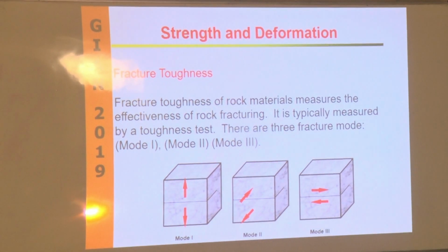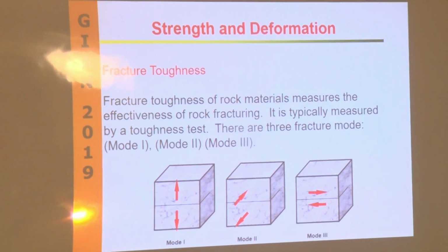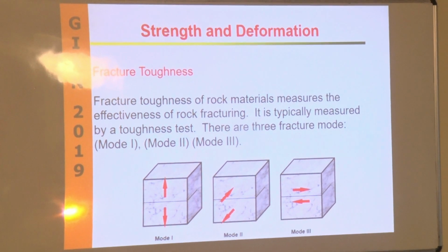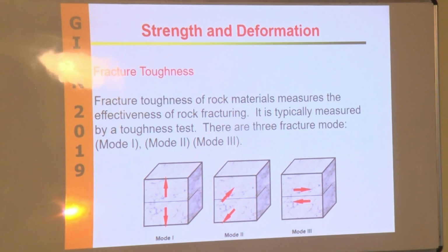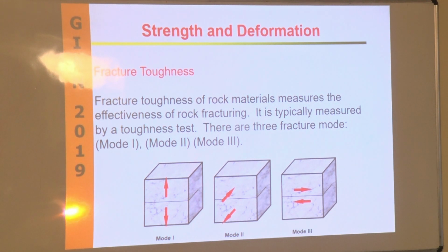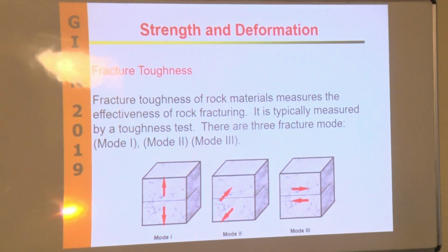Say that macroscopically shear mode exists, because definitely you have displacement along those fractures, but that is a coalescence of very small tensile fractures. How do you deal with that? Well, you do a compromise, you sort of accept mode 2, but I still don't. Many groups are also claiming that they are going to produce mode 3 then. Good luck.